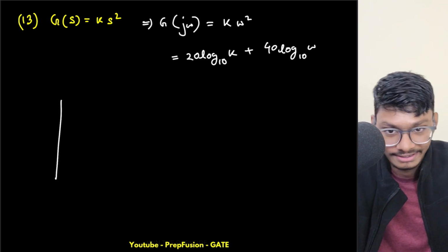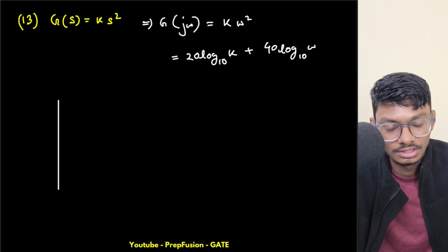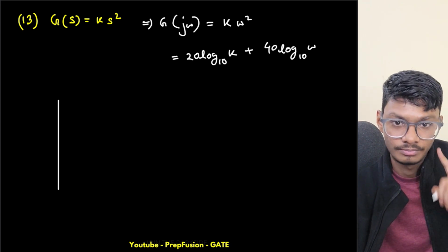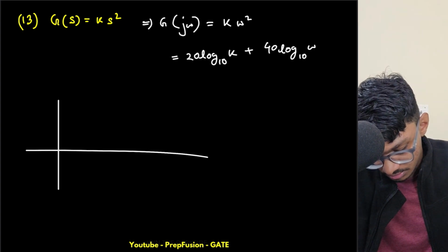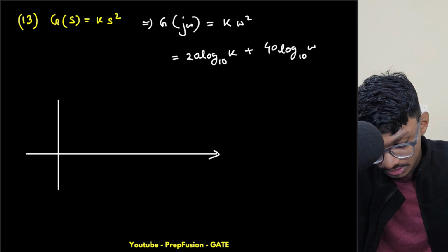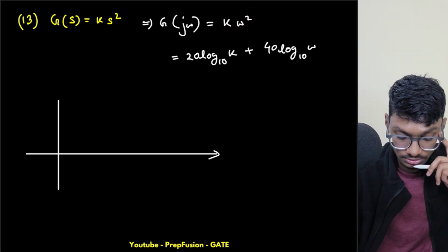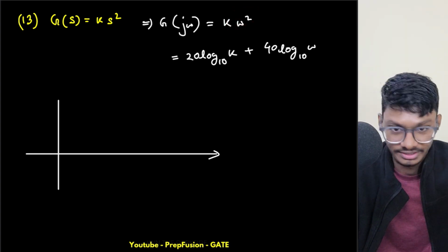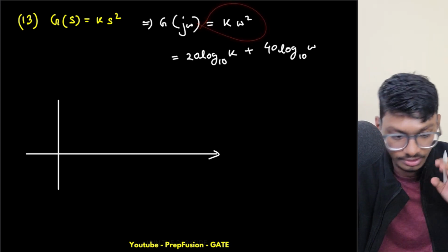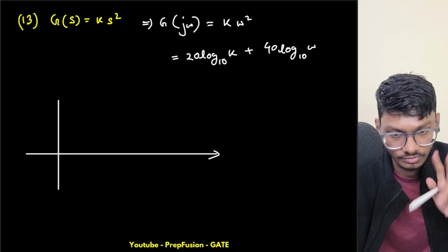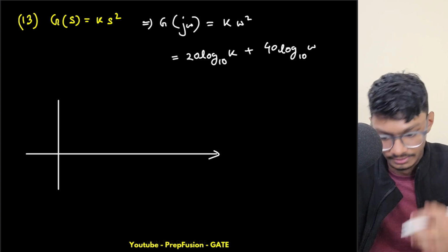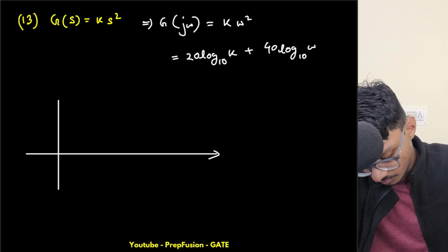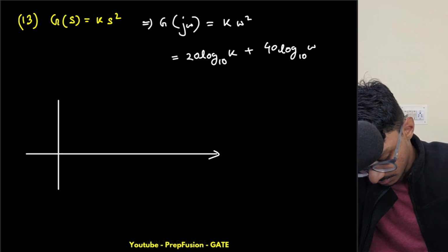What is the slope? So like what is the angle here? Angle this time isn't minus 180 degrees. This time plus 180. Okay, plus 180. Or you can say, sorry, this time, how much angle is this? Oh sorry, this is also minus 180. This is also providing minus 180, like plus 90 times 2. Minus 180 or 180 is the same thing. So we'll do the angle thing, but first let me plot the Bode plot, gain plot.